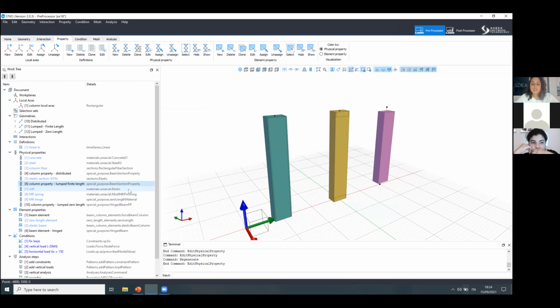And then this kind of property can be assigned directly to the beam, and we have our finite length plasticity approach. In order instead to build our zero-length plasticity approach, we have to construct the phenomenological law. This can be sometimes daunting because you don't know where to start.